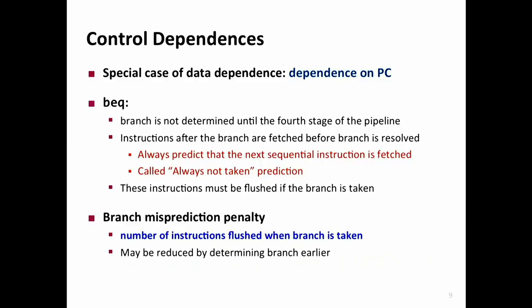But of course, now you can start being smarter, right? You can say, oh, why don't I distinguish between different branches? Maybe this branch is always taken, this branch is always not taken. So now, based on the program counter, I have separate predictions. Now it starts getting exciting and more complicated also.